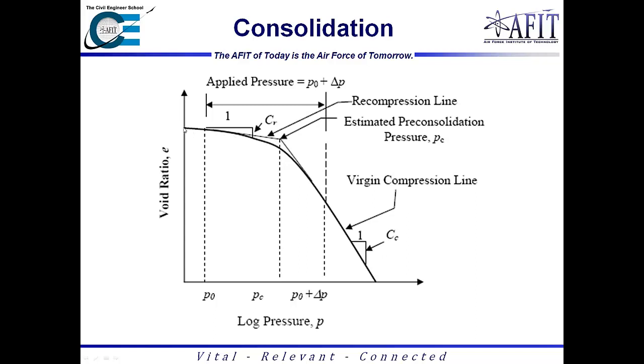And the main reason for that is because in this part of the curve, the soil is still considered elastic, i.e., if I loaded the soil up to this pressure but not to the pre-consolidation point and then suddenly unload it, it would come back to this void ratio. However, once I get past the pre-consolidation pressure and say I went to right here and I unloaded it, it'll unload, but it'll unload to a value less than the void ratio. And the reason is because the soil has technically yielded at this point. I've now pushed it beyond the elastic state, and so there's now an over-consolidation that's happened. And so once I've pushed it past that point, I can't go back to the unconsolidated state.